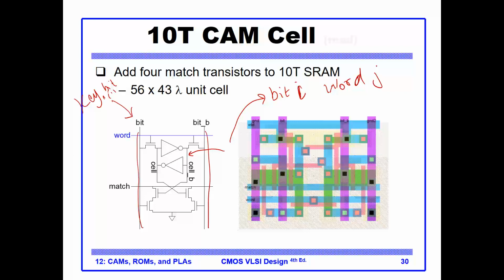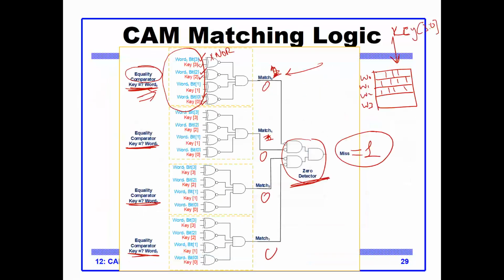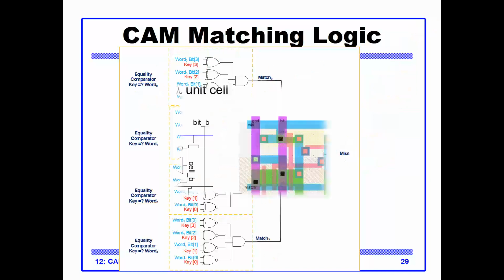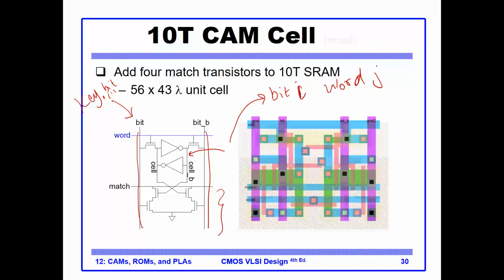And what happens? I implement here the XOR. Now you will tell me, wait, but we are using XNORs, right? Yes, but we will do bubble logic here so that we can save inverters. So we will use an XOR.